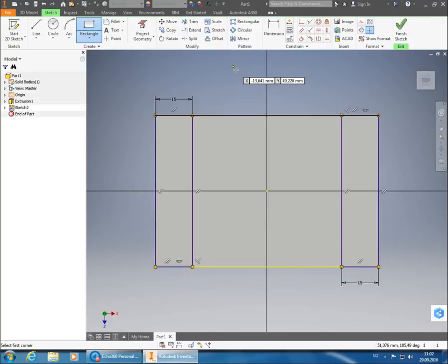And I can check that it's locked into place by exiting the rectangle function. And I can see that it's fully constrained down in the corner. So it says down here that it's fully constrained. So then I know that everything was locked into place when I did this. That was what I didn't check a couple of times last week, so that I had some problems when I was doing extrudes. So I didn't check that they were fully constrained before I exited and tried to extrude it.